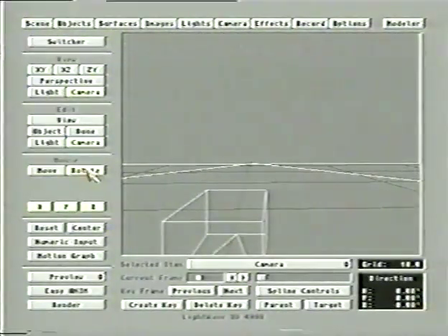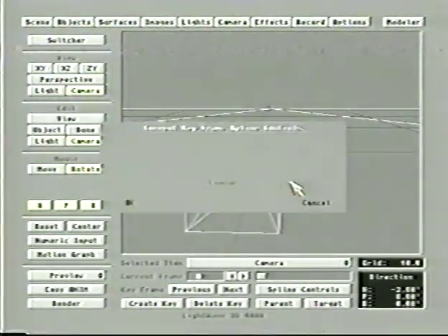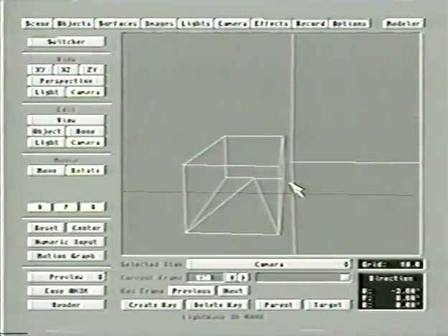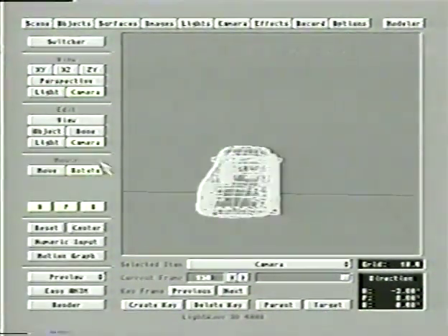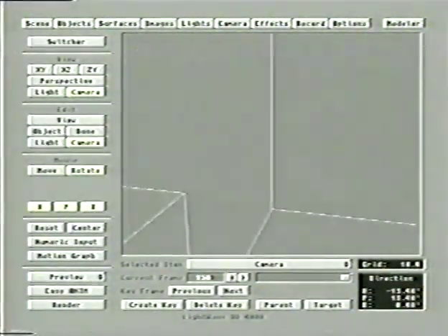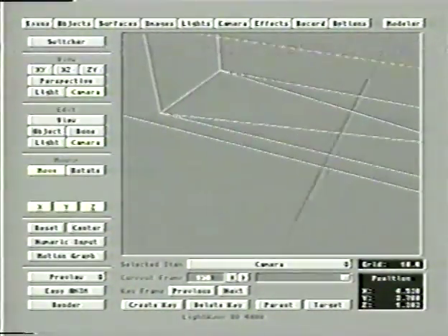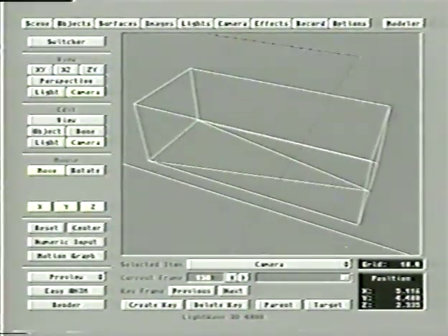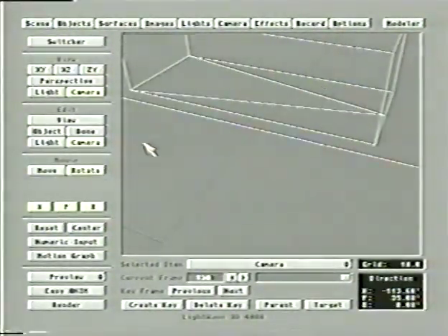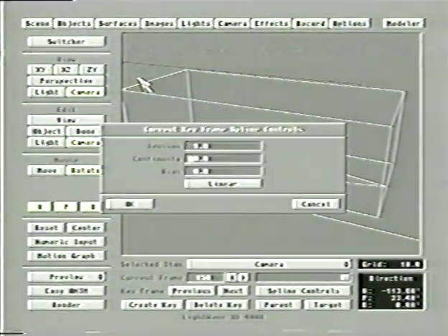I just quickly get the camera into position. It's already parented to the car. Keyframe it here at 0 with a spline tension of 1. Then we'll go to frame 150. And at that point, we'll want the camera forward a little bit and aimed to one side. Let's back it off a little here. And again, just keyframe it here. Spline tension of 1 as well.